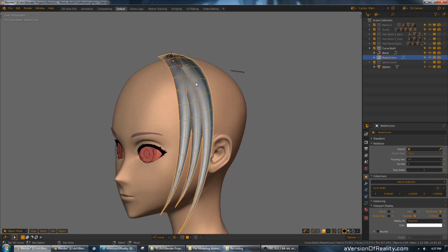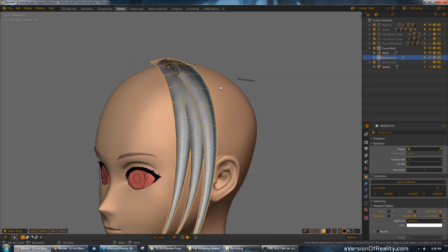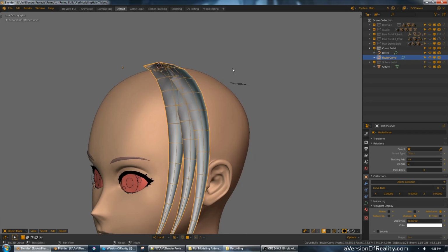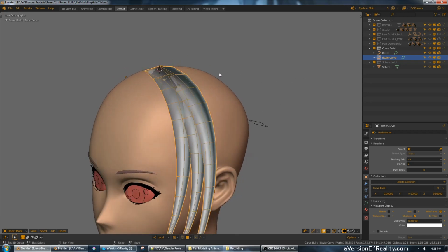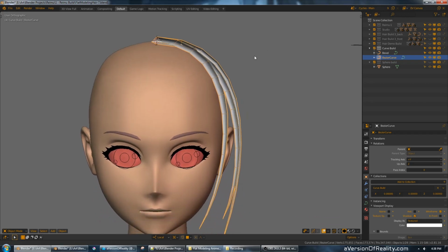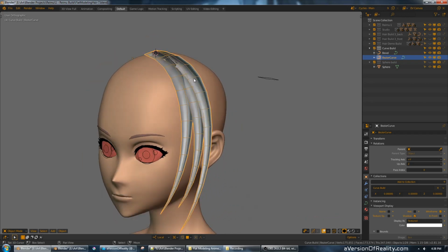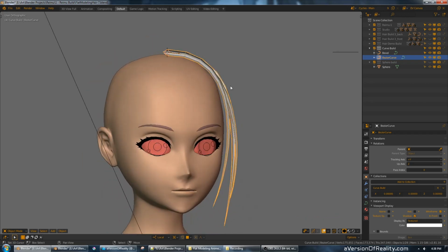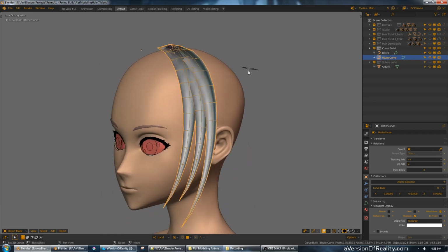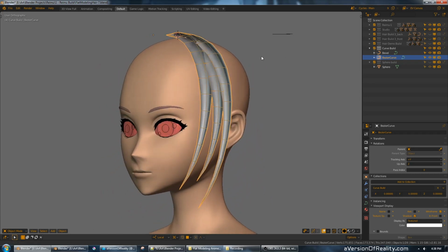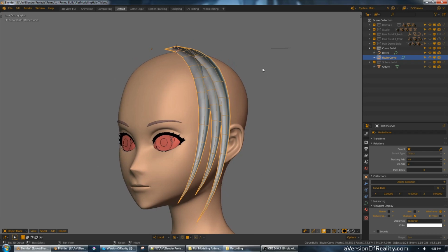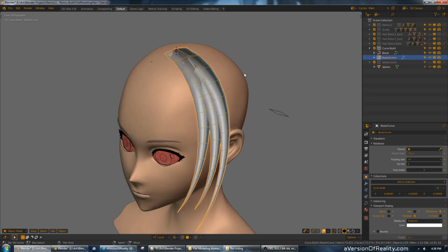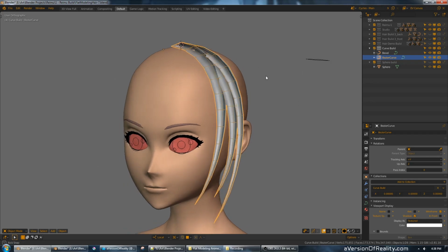And usually what people do is merge these together with sculpt mode or dynamic topology. They'll boolean them together and then try to clean them up, but then it's high poly and you have to retopologize it, which is hard on a strandy, sharp edge shape, and it's hard to get a clean UV unwrap for it. And so even though it's quick for the initial setup, it's very time consuming to actually get clean results and get to nice clean topology.